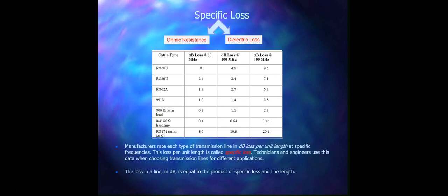And it becomes severe when you are working at a higher frequency. Because at higher frequency, the circumference of the wire becomes much more important than the cross-sectional area, which means that the effective resistance of the wire will increase as the frequency increases.